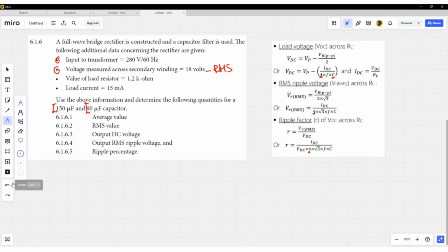In fact, you can see this in the other form of the equation, right? That's your voltage peak to peak. That's going to be influenced there. So the bigger the capacitance, the smaller your voltage peak to peak is going to be. You can also see here in your ripple voltage calculation as well. Increase the capacitance, you're going to have less ripple for a given current.